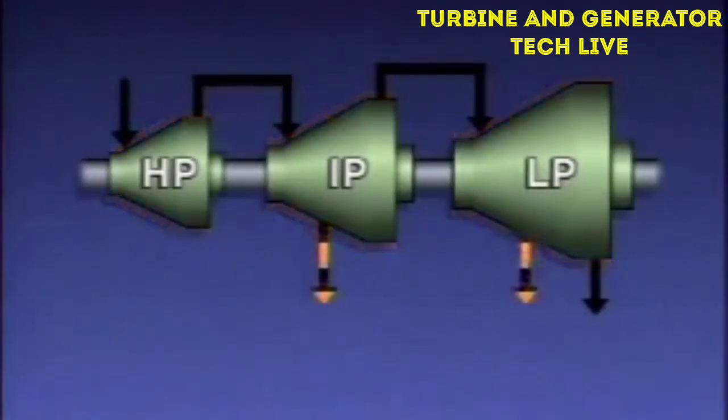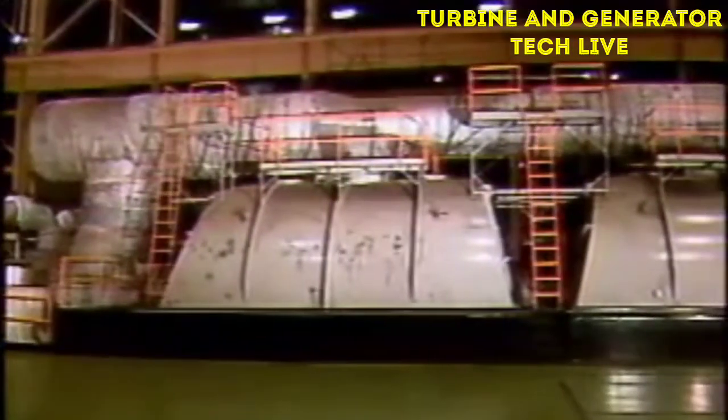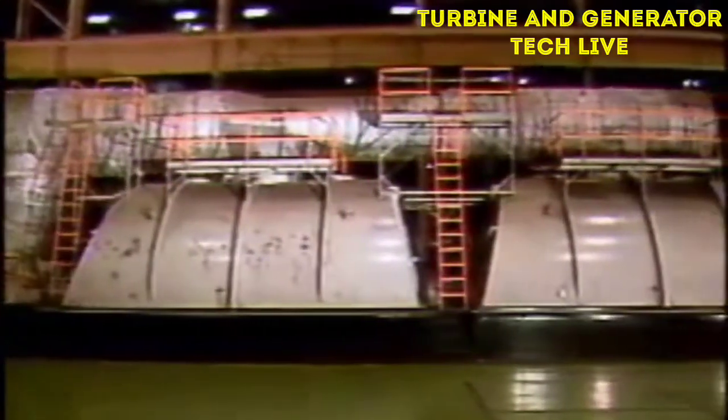Second, some of the steam is removed from the turbine by an extraction steam system. The extraction steam is sent to the feed water heaters, where it is used to heat feed water. The steam in the turbine gives up some of its heat as it passes from one stage to the next.